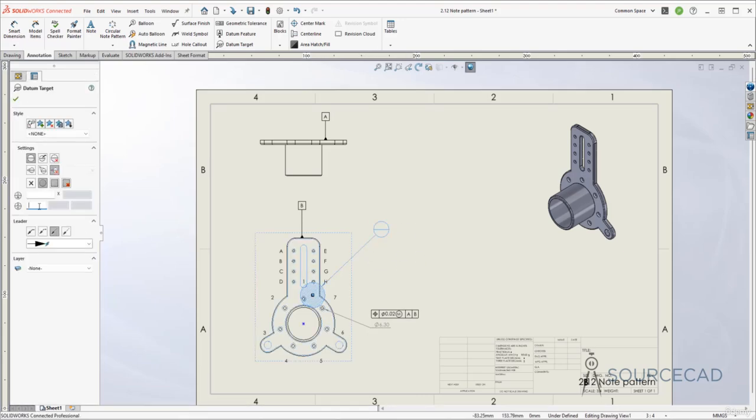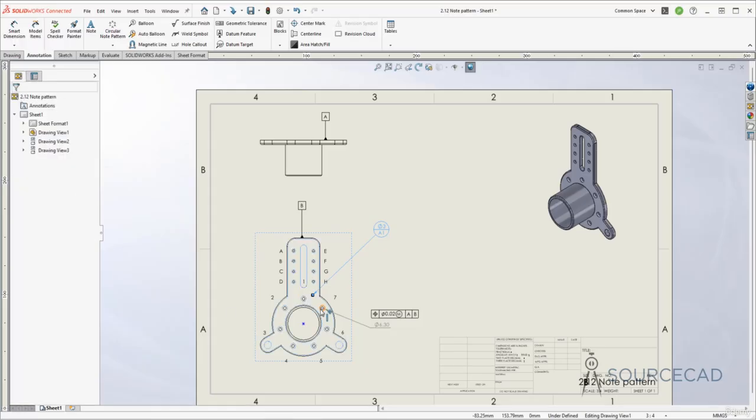Now I'll select this and make the modifications. The first one here is the datum identifier. So it should be, let's say A1 is what we are selecting for this, and then you can select a diameter value, for example 2. When you select the diameter value, it will automatically change the size of that hashed area as well. So based on whatever diameter value you're entering, maybe 3 is just going to make it a bit larger, and with that click OK, and here we are.